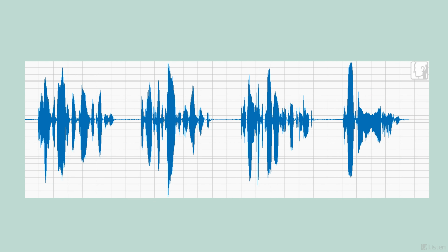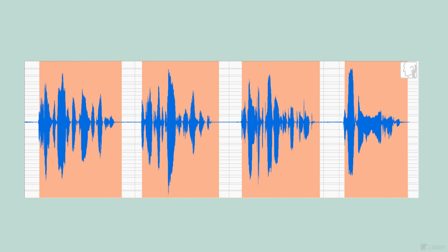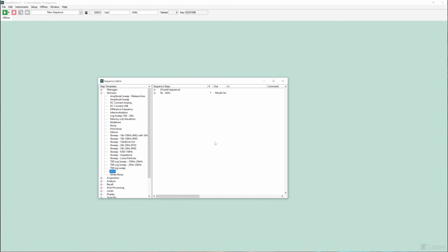When active speech level is used, signal levels are scaled using only the parts of the waveform where speech is actually present, rather than the overall RMS level. Silent gaps are excluded, but utterances that are part of normal speech are included. This removes variability due to different speaking speeds and content when making measurements. It provides better consistency for standardized measurements.